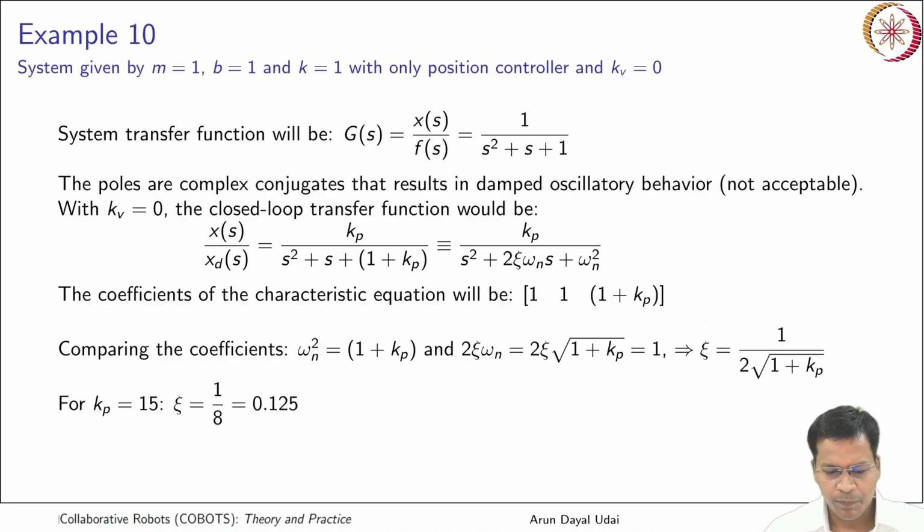Okay, so now I can do this quickly. Let us analyze the critically damped condition, you know gains can only be positive. If I take xi as 1 and square both the sides, it should take you to 1 by 4 equal to 1 plus kp. So kp can be calculated like this. If I just calculate it, I see kp comes out to be negative. So it is not possible to take it to critically damped condition with just proportional gain. Okay, so I'll do something else.